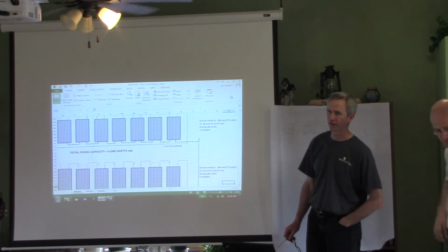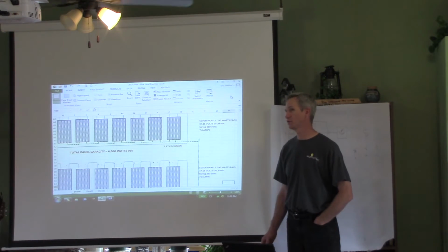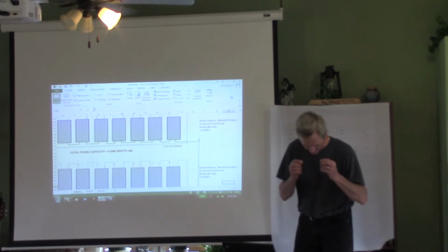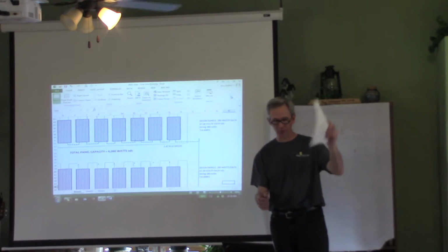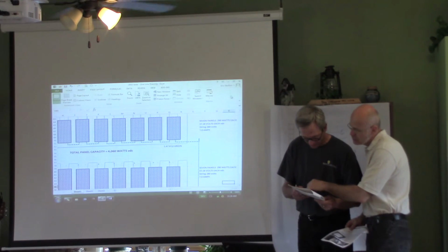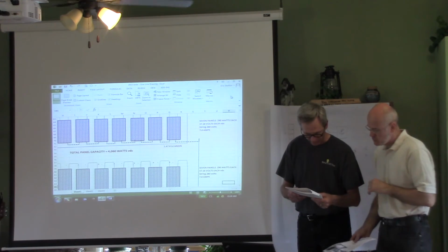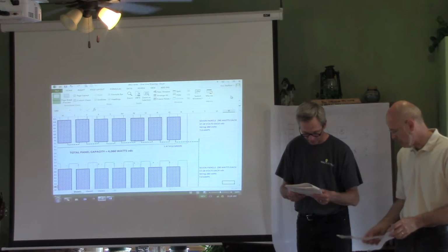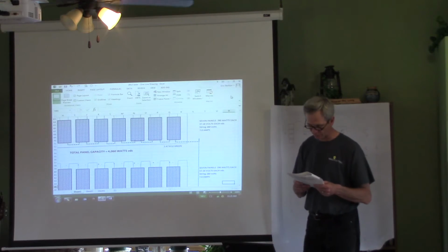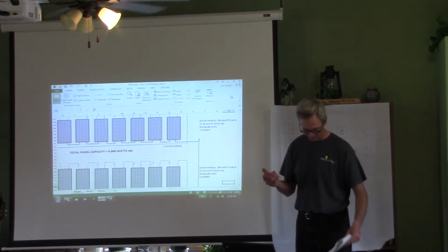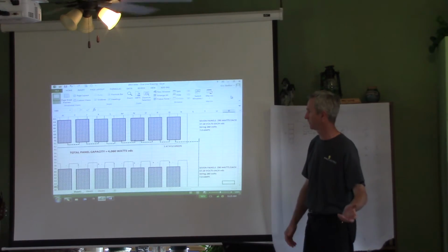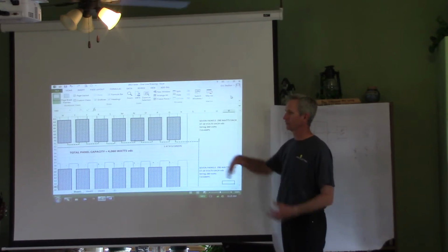So 7.8 amps was okay, but then I have 2 strings. He talked about it before. Put those together, and I'm under the max for the inverter again. Yeah, for amperage. And the max, down here under DC, it says max input current, operating current is 21 amps in this particular 4.4. And we're at 16 currently. Even if we up it by 20%, we still stay under, as he covered before. So those were the things we had to balance.